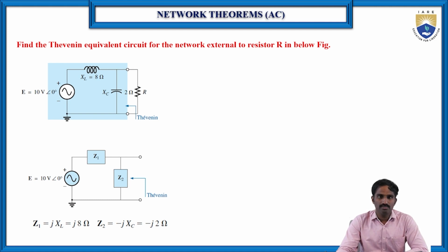In Thevenin's theorem, we find the current flowing through the load resistor. First, it is very important to know how we convert the whole circuit into the Thevenin's equivalent circuit. The Thevenin's equivalent circuit has the Thevenin's voltage and the Thevenin's resistance in series with the load resistance RL.